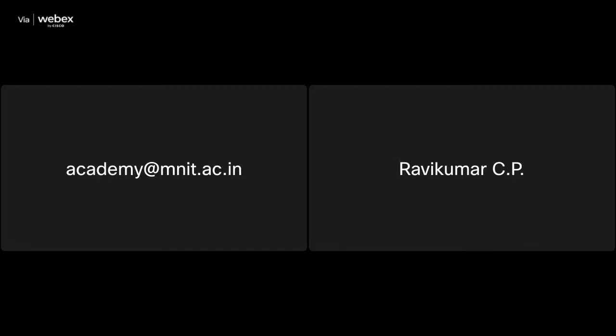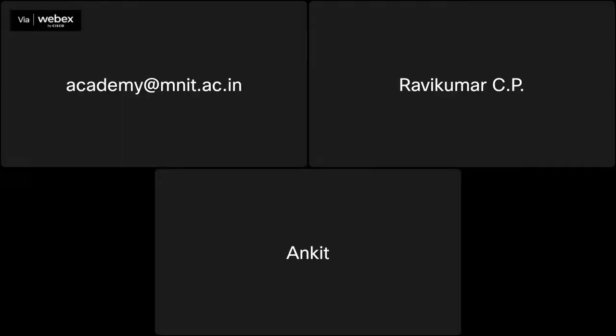And we decided to write a test bench called sub4 test. And here we declared A and B as 4-bit registers and the borrow as a 1-bit register. And diff is a 4-bit wire and R out is a 1-bit wire.